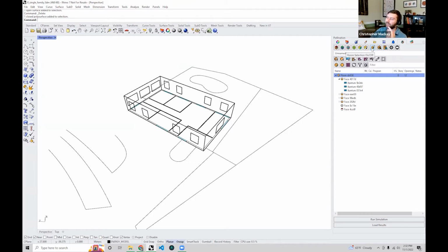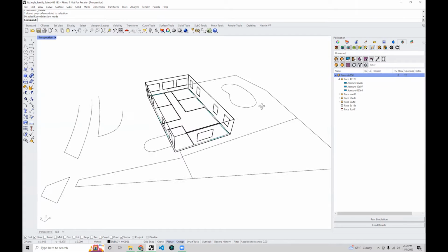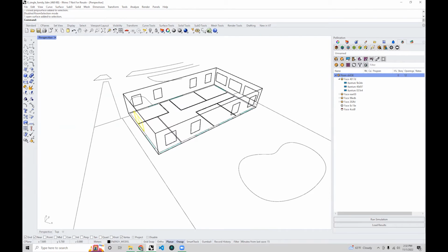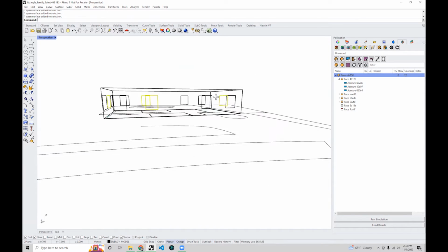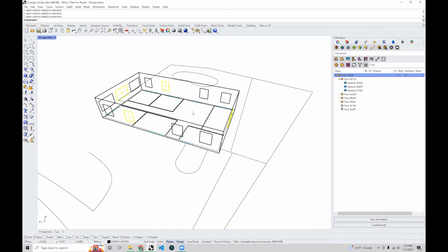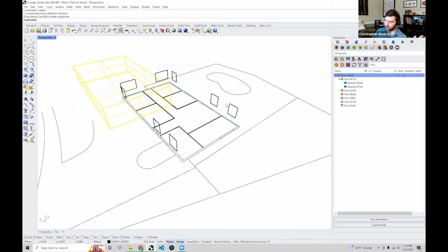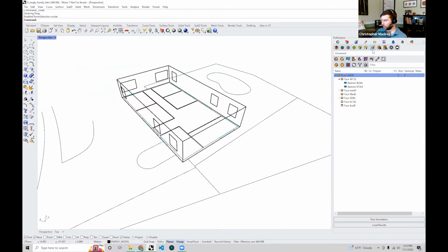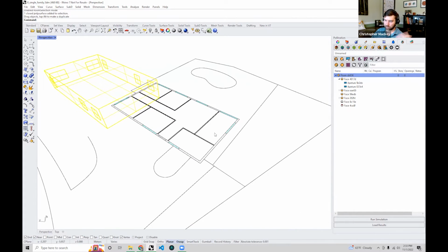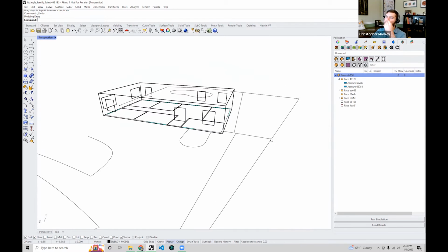Room selection. Ah, okay. So if you click on this, you get the same selection ability for the room, but now you can do it for several rooms at the same time. Use it when you want to do this kind of edit, because in this mode, if you move the room, the apertures are not going to move with the room, because the selection mode is separate. Whereas if you have room selection on, which everyone following along can leave on, if I do this, then the apertures come with the room. Yeah, that's a really useful feature.